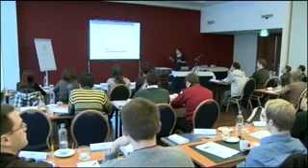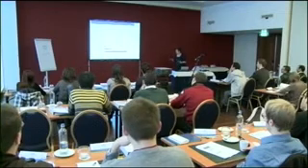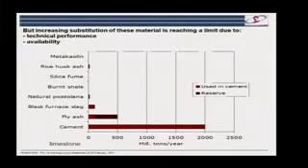Well, you see there's a large number of materials out here which are used today in very, very small amounts. Their amounts could increase. And particularly, I think it's interesting that this material called metakaolin, or more generally calcined clays, that means clays that are heated up to about 600 to 800 degrees, this can give an active material you can use in cements, and clays are available almost everywhere in the world.